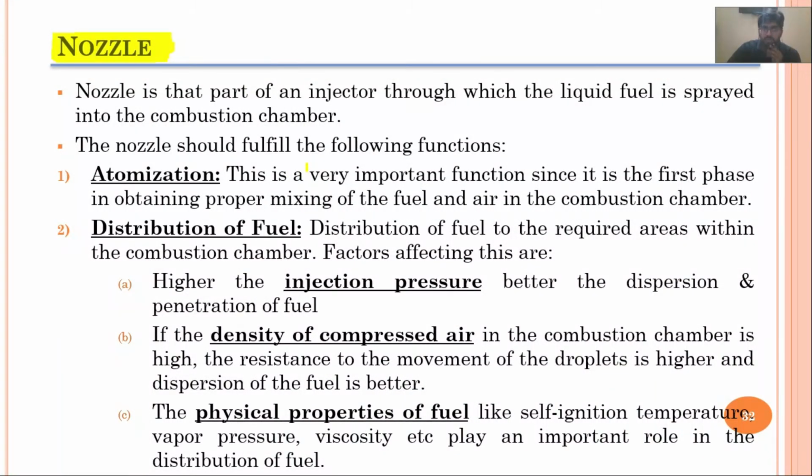The nozzle should fulfill the following operations. Number 1, atomization. As I mentioned earlier, fuel should be atomized for better mixing, and fuel is coming at quite a high pressure, so it is very important that we atomize this fuel in order to have a proper mixing. This is a very important function, since it is the first phase in obtaining a proper mixture of the fuel and air in the combustion chamber. So a nozzle should ensure the atomization of the fuel.